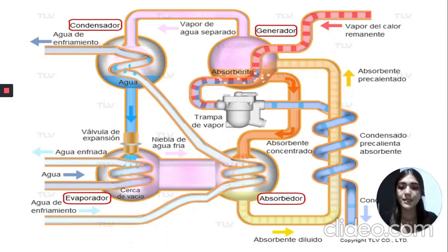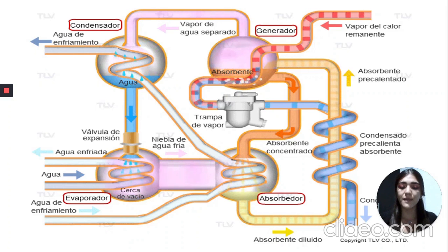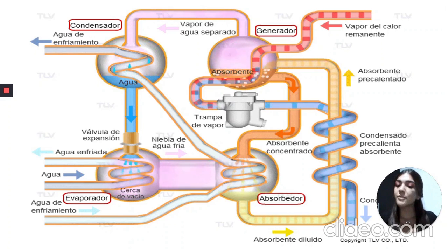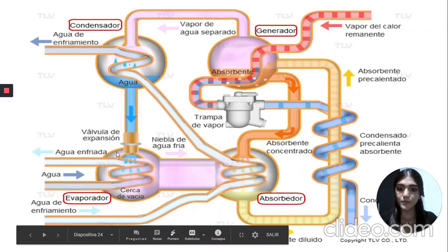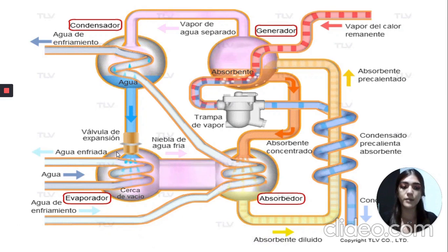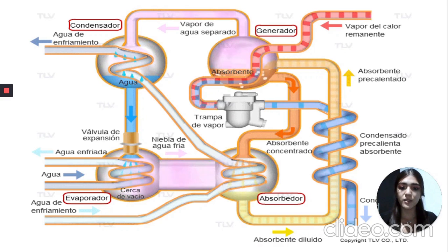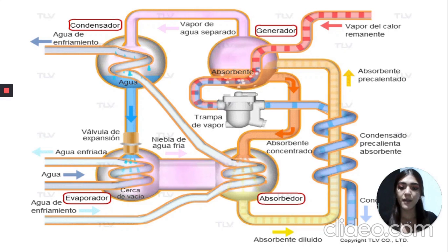The vapor lowers the temperature and extracts the heat from the chilled water circuit, reducing its temperature by approximately 5 degrees Celsius. Number 6. The mist heats up when it absorbs heat from the chilled water circuit. But the strong attraction of the concentrated solution pushes the water vapor towards the concentrated absorbent, creating the vacuum pressure of the evaporator in the process.